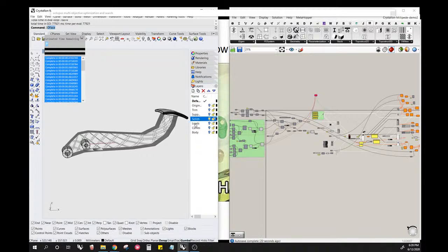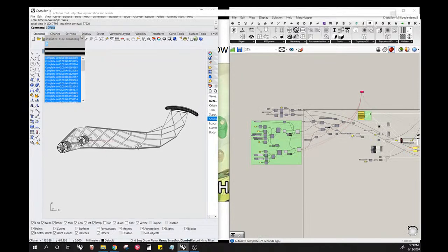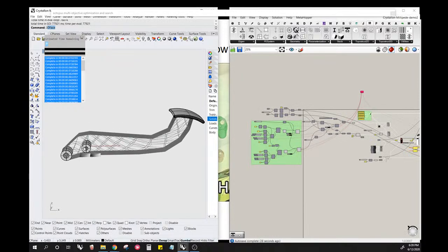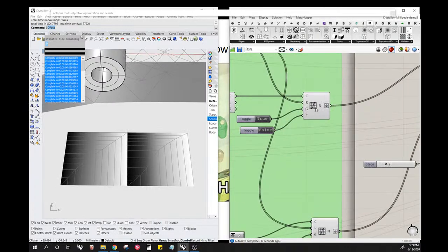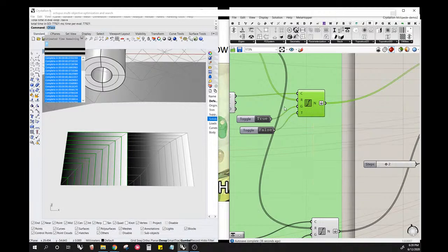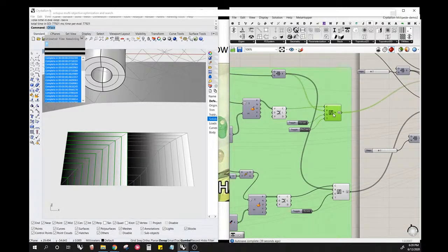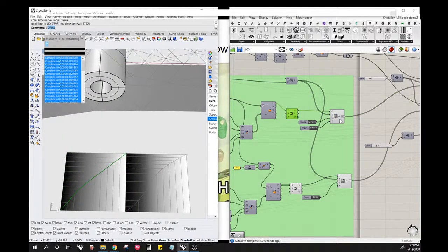And what we start with is playing with just the divisions. Here I'm using, again, another component that's not released in the latest Crystallon, but it is on GitHub, in the version 2.1 folder. It's basically like the graph mapper. It's reparameterizing values based on a curve. And I'm creating this NURBS curve from points.